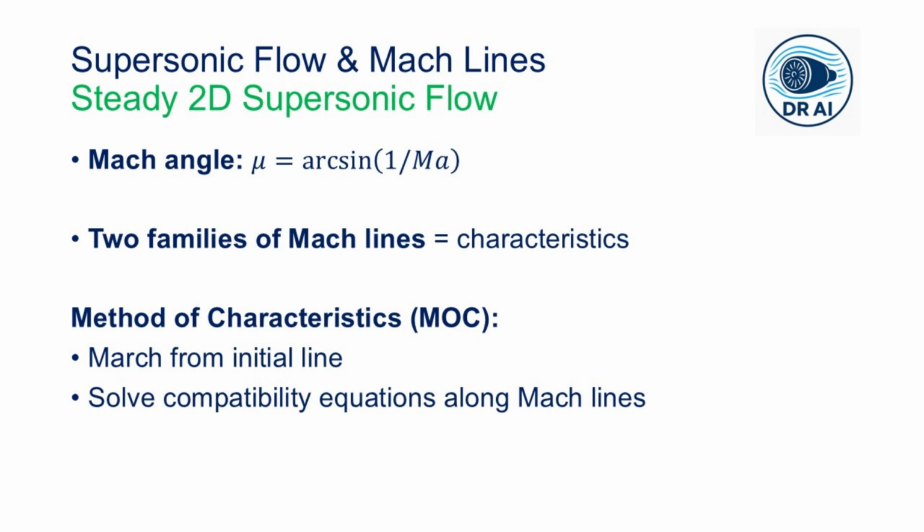And here we have a question. Suppose we have the 1D Euler equations for compressible flow. How many eigenvalues must that system have, and what is the physical meaning of each? The answer is three eigenvalues. Lambda 1 equals u, which represents the material derivative or the contact discontinuity.